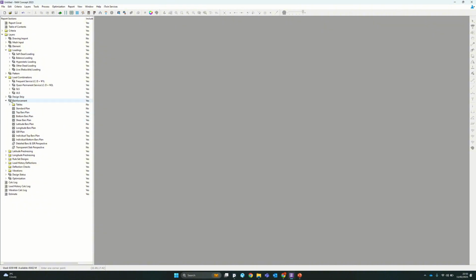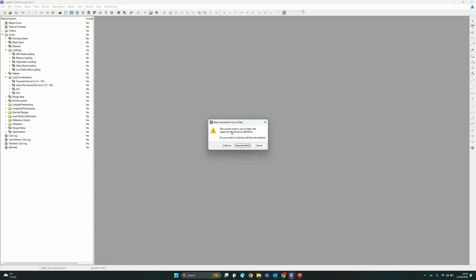If you were just looking to do a basic analysis of the loads being distributed throughout the model, the element, you could come up here to either one of these. I usually use partial, because things have changed and I need to generate the mesh again, that's fine.